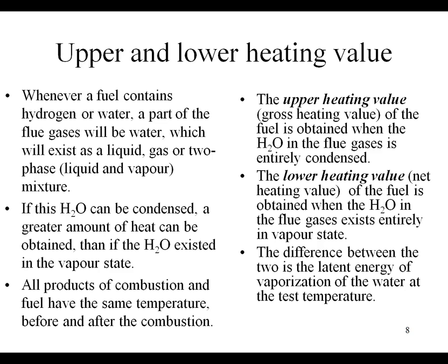So the flue gases contain a lot of gases, CO2 and nitrogen, and what else? I ask you. Oxygen. Oxygen, yes, and? Carbon. No, carbon, no. Humidity, vapors. Oh yes, humidity. Yes, vapors. But if these vapors remain vapors, it is okay. But if these vapors are condensing, this phenomenon is also exothermal. And normally, if you cool down the flue gases, the condensation occurs.